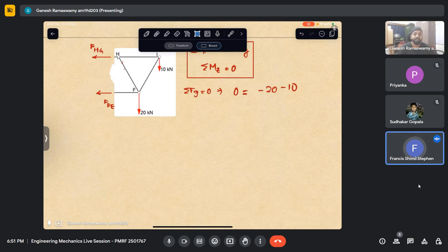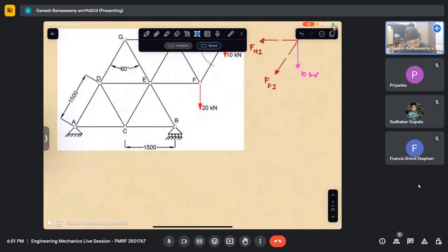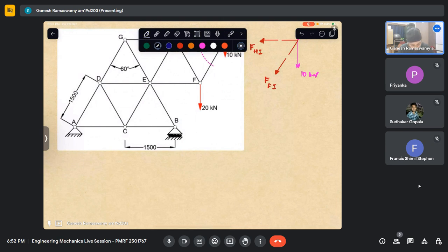Yes, it could be. Over constraint means you have provided, if I put, instead of a roller, let us say I don't allow it to roll, then this becomes over constraint. Over constraint meaning whatever is the bare necessity to keep this in equilibrium, over and above that I am providing some support conditions. Are these needed? Yes, these are needed. Does this have any effect on the forces? Yes, that will also have.